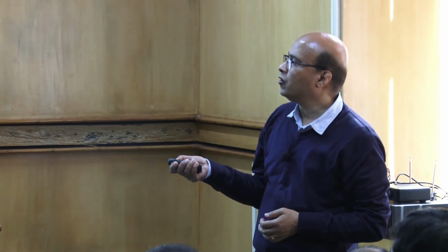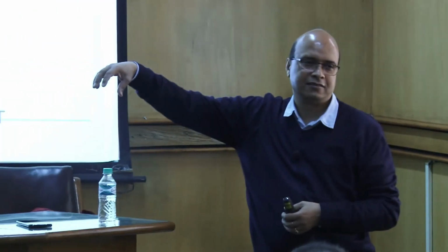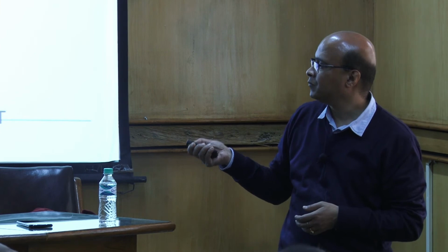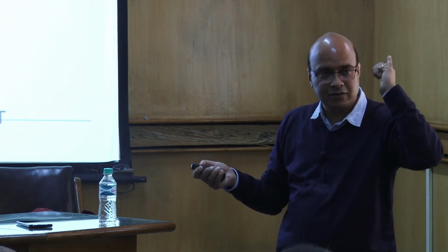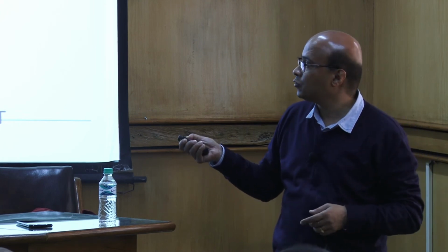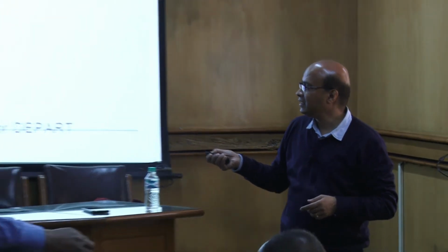Draw. Draw means after I've gone here, suppose I find that it was not exactly correct. I want to make a small change here, here, or here. Then we can say that you draw from the last position 45, 56, 60, so that it makes a small correction on the previous command. This is an incremental command, this is an absolute command. This is absolute, this is incremental.